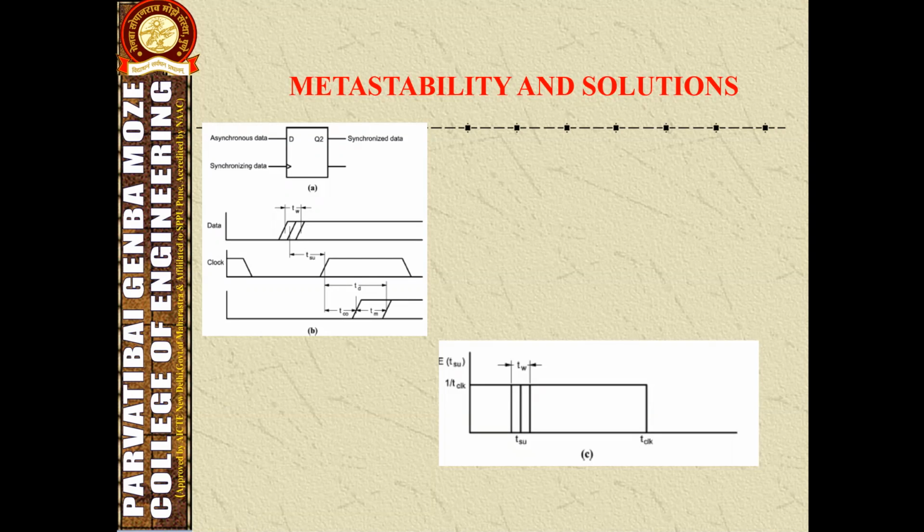The relationship TW equal to F of TD is used for defining the metastable behavior of the flip-flops, and the exponential function is asymptotic, valid for the relation as shown below. TW is equal to F of TD, which is equal to A times exponent of B into TD.